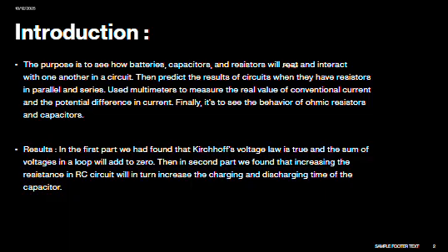And for the results, in the first part, we found that Kirchhoff's voltage law is true, and the sum of voltages in a loop will add to zero. Then in the second part, we found that increasing the resistance in the RC circuit will in turn increase the charging and discharging time of a capacitor.